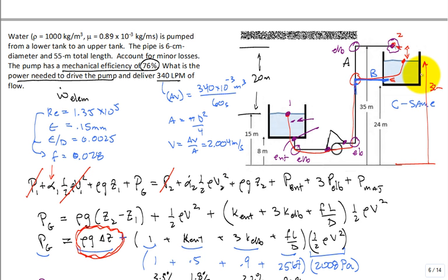Does the pump have to fight against the water in the top tank pushing back on the pump? That's modeled as the kinetic energy dissipation of that submerged inlet. No, it's included. But it's going to have the same effect as it being kicked out with kinetic energy at the unsubmerged outlet.